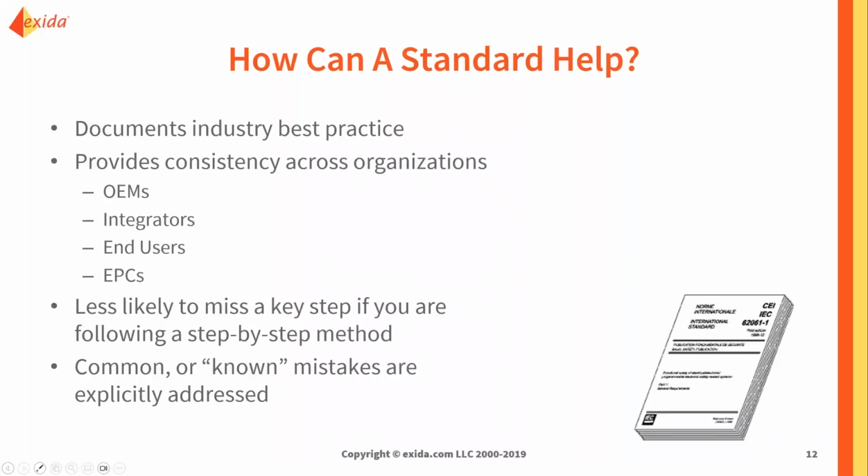And so it can help us really identify and say, okay, if we ask for a SIL 2 system, that means the same thing to the integrator, the end user, and the product supplier that's looking to develop a SIL 2 component. Also, if we follow a step-by-step lifecycle approach, we're less likely to miss a key activity because we're going in a consistent pattern.